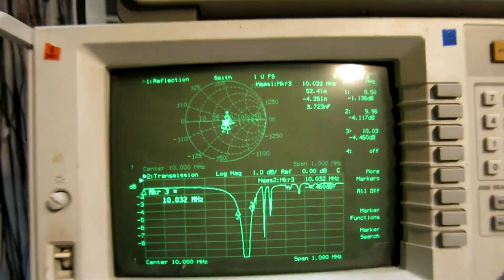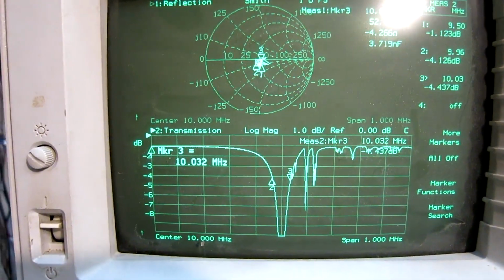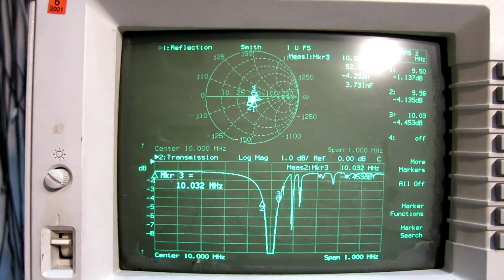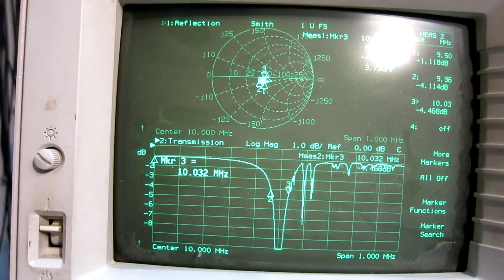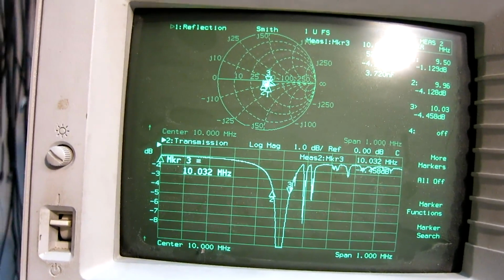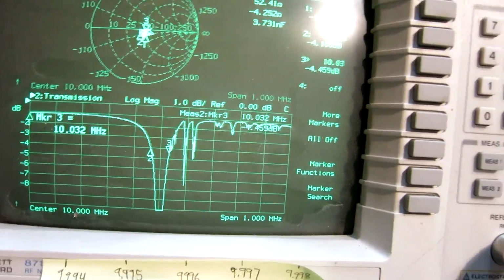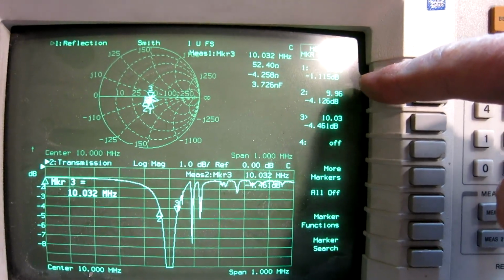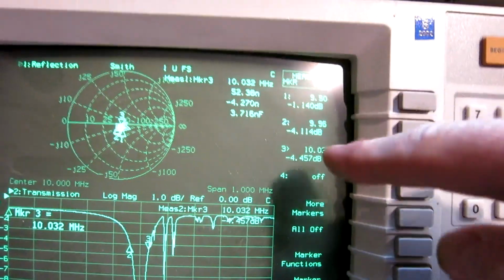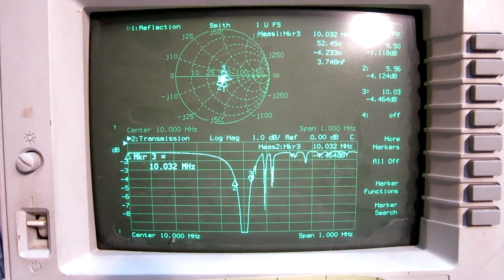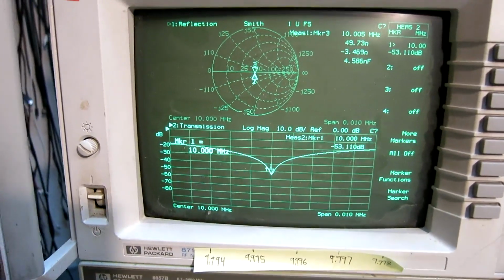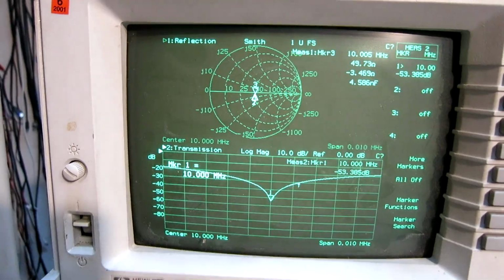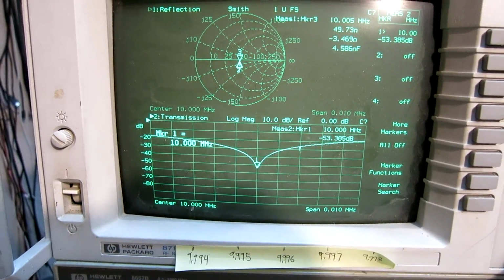And then I look at what I have. Firstly, the impedance is close to 50 ohms over the entire range that I'm looking at. It's plus minus 500 kilohertz. The useful bandwidth for me to measure sideband noise is between the 3 dB points of the notch. It is 2 and 3.3 dB below the attenuation I have 500 kilohertz away. And that is something like 8 kilohertz. It says 7 here, but I have to look more carefully later on. A close range view, I'm sweeping 10 kilohertz. I can see that the notch is 53 dB deep and the impedance is very close to 50 ohms. And that will be for the carrier under test.